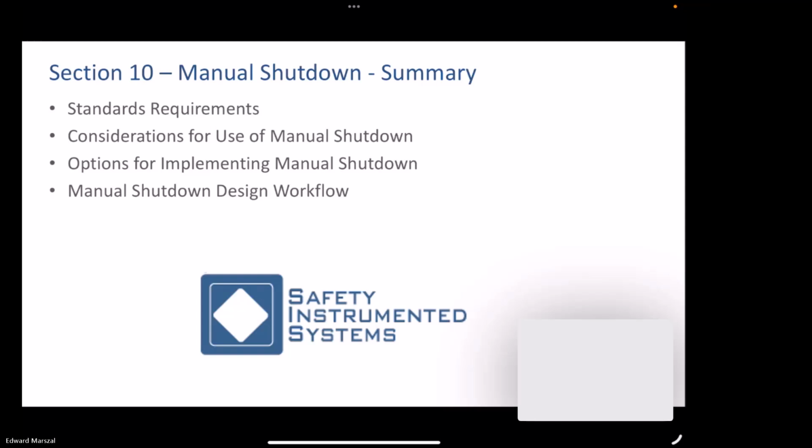Okay. SIFs with pre-alarm, what is the assurance that the operator will not take action during pre-alarm but can take action of manual shutdown? If I have a function where I have a pre-alarm and the operator didn't do anything about it, and then my safety function activates, but the valve doesn't close, why do I think that the operator is now going to push a button and close that valve?